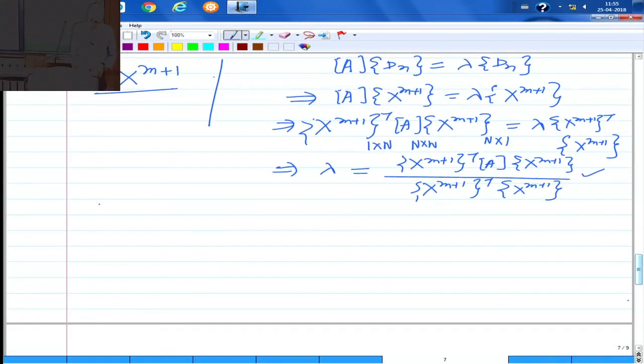Suppose now I have got, using the inverse iteration approach, the first frequency, omega 1 let me say, because n I am using as a subscript, and the corresponding mode shape d1. These I have got. And now using the same inverse iteration, I want to get omega 2 and the corresponding mode shape d2.